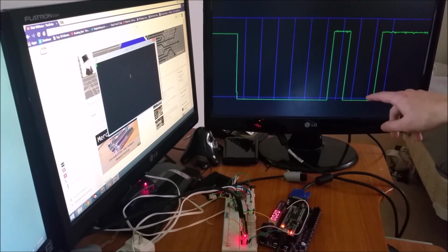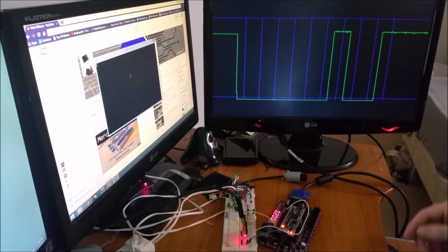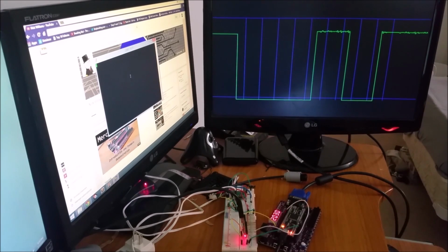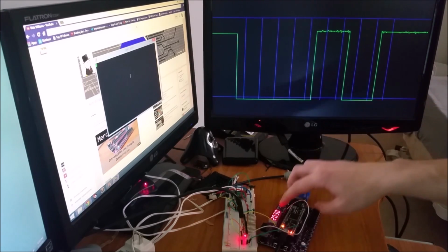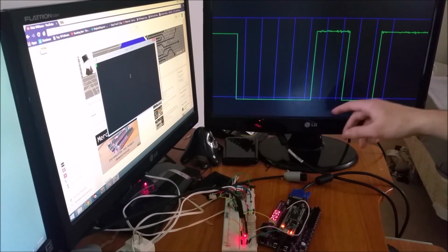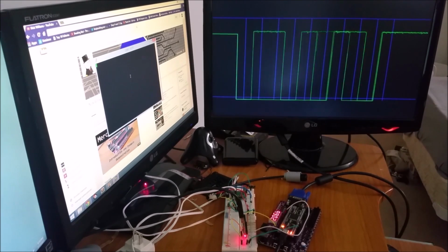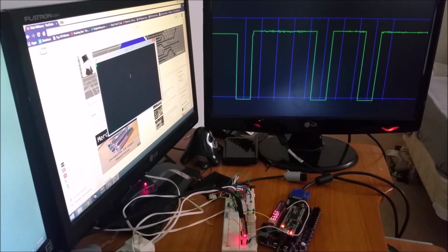So like I said, it reads 20, which is 0010 0000, so 20. If I actually push the key 0, I'll get 30, which appeared on the 7 segs, and then you get 0011, which is 3, and then zeros for 0. And 1, 2, 3, 4, 5, 6, 7, 8, 9. And even if I type in a bunch of random characters on the keyboard, it'll still be able to, well, at least it appears to keep up.